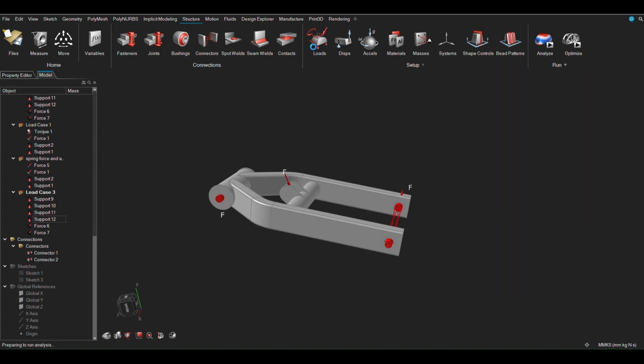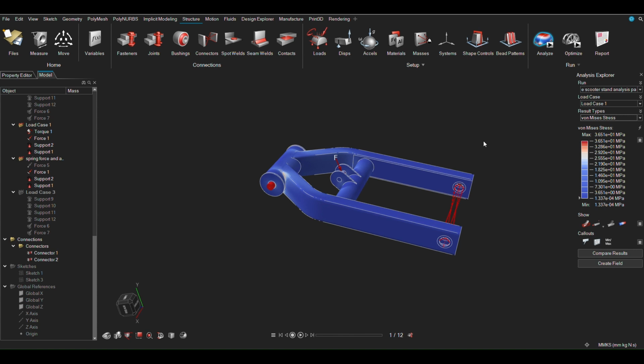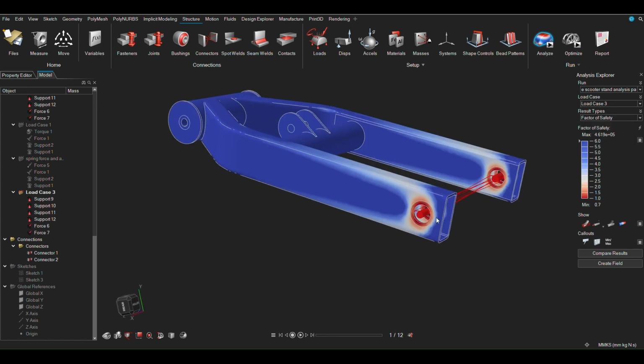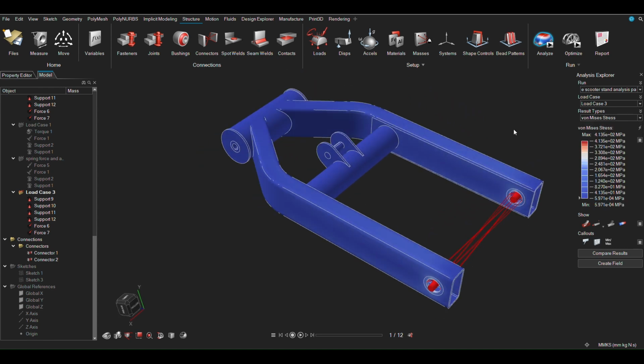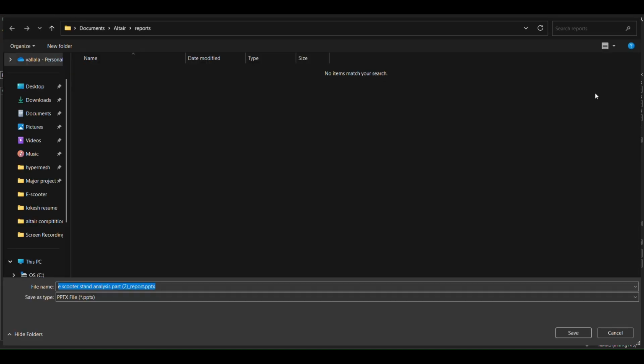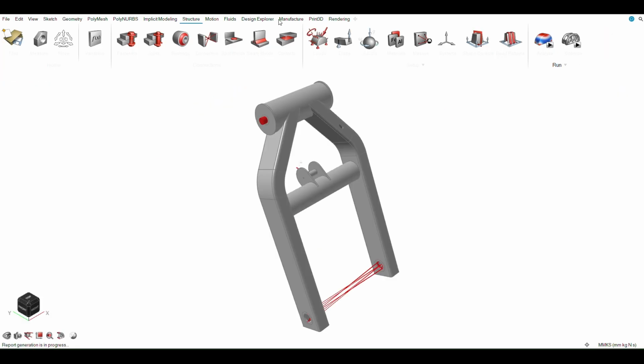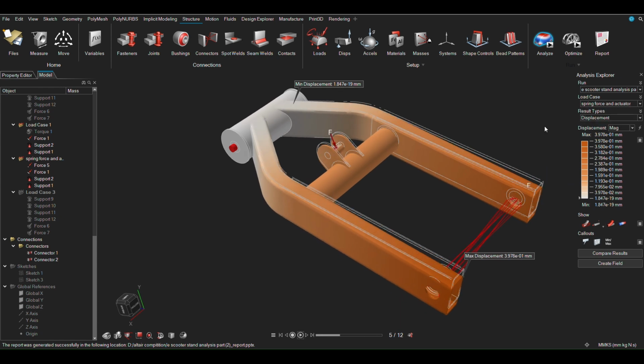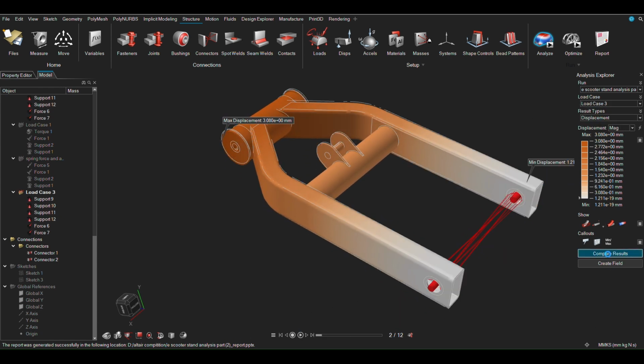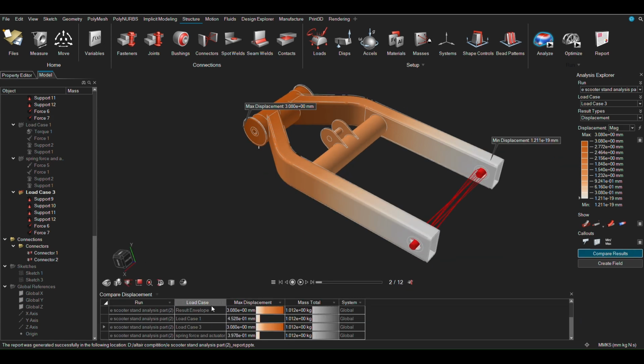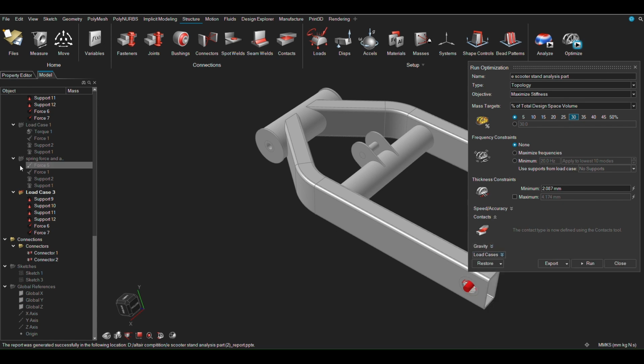By comparing the multi-motion dynamic analysis for the swingarm and a separate static analysis on the isolated swingarm, I compared the factor of safety and von Mises stress values from both methods. The results were quite similar with only minor variations. These differences are expected since the motion simulation was run in fast mode to save time, instead of accurate mode. In both cases, the von Mises stress remained well below the yield strength of aluminium, which is 324 megapascal. The factor of safety was also good.